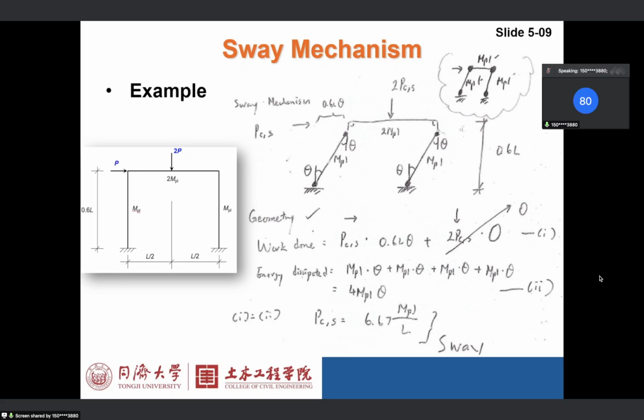Sorry, I didn't quite get what you mean. For example, you said there's a beam mechanism and a sway mechanism. When we used to do the analysis as undergraduates, sometimes we might add beam plus sway mechanism, right? And if, for example, we want to find the final angle, we might have minus theta and plus theta.